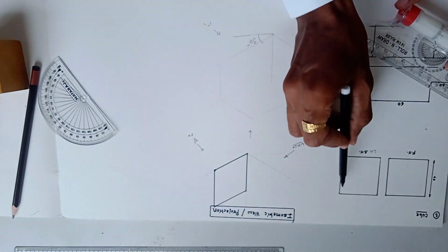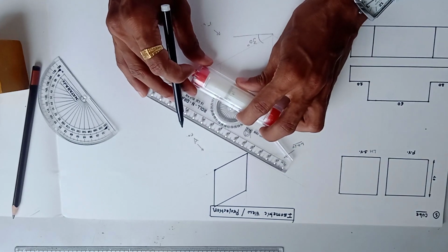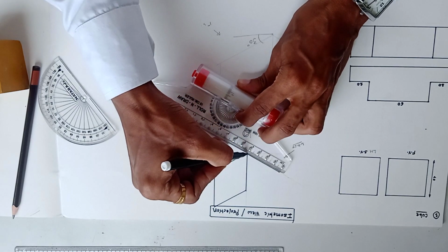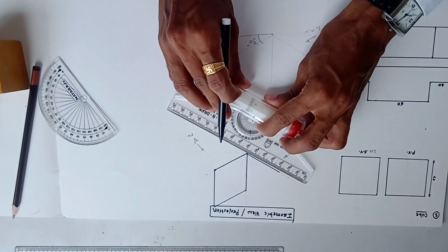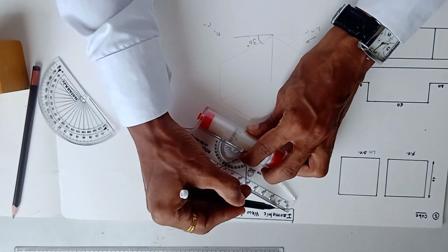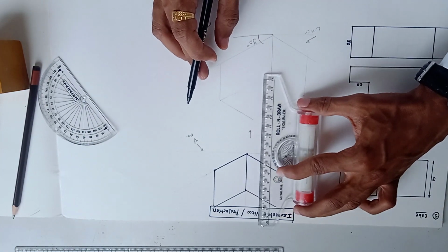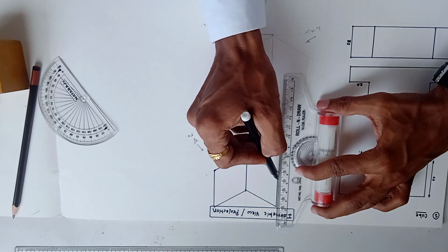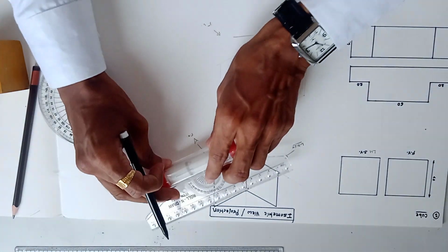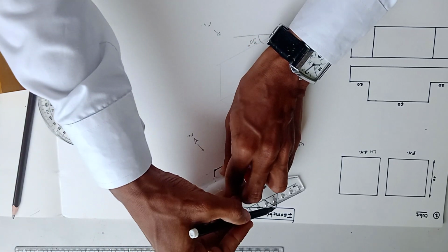Now in the side view, again we observe the square with the same dimension. So this is the width in the side view. This is 40 mm. Now from this line, you can draw the parallel line, and from this line, draw the parallel line. So this is the visible outline in the left-hand side view, and then you can complete the top view. The top view will be a square only.